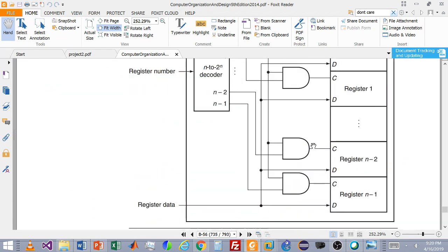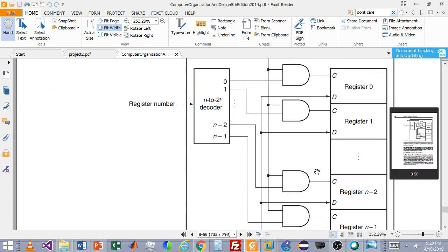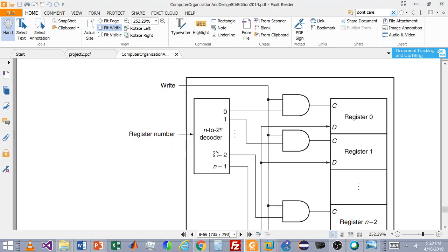The write portion is very similar, except what do we need? Well, we need to know the address again, so we'll have some decoder with the address. And this is similar to the example I showed in the previous video with ROM, right? How we do the decoding with combinational logic. And then we have an AND here, our AND plane, for writing.